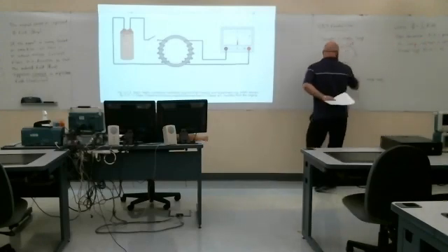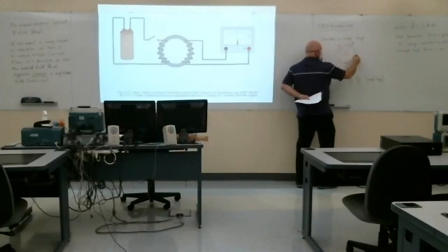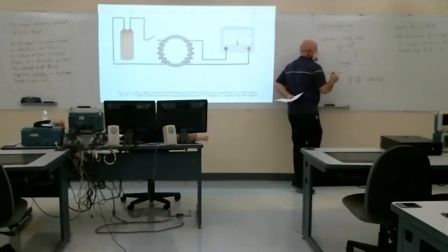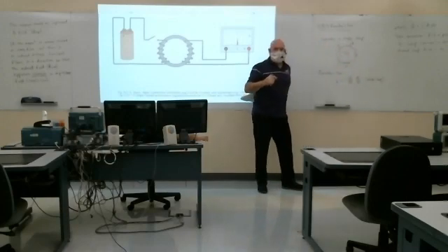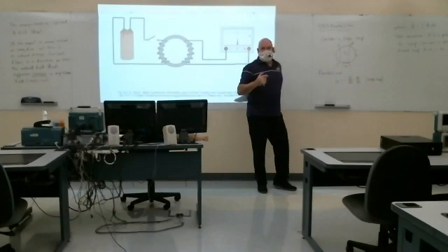So again, once I pick this, that determines my contour direction. Plus minus, again, it's from the minus around the loop to the plus. So my contour would be in the counterclockwise direction in this particular loop.